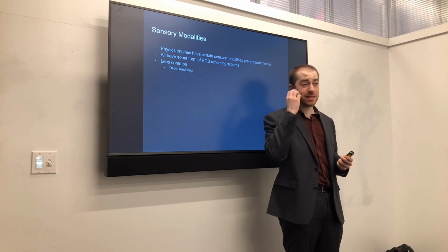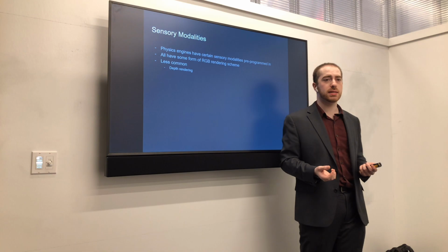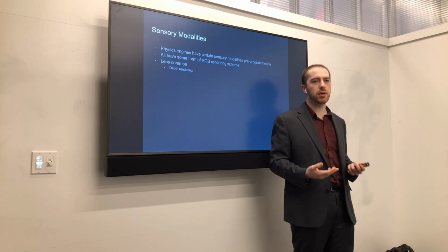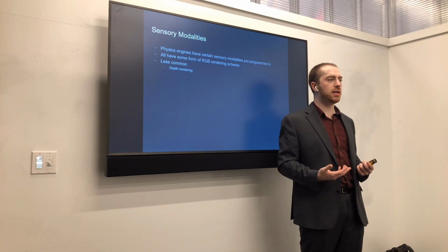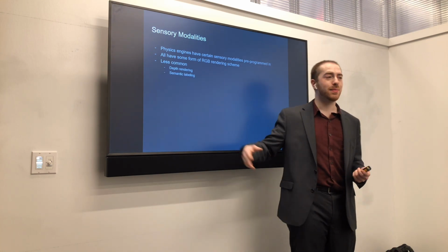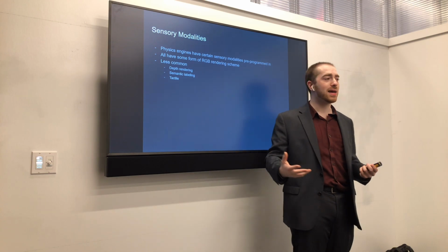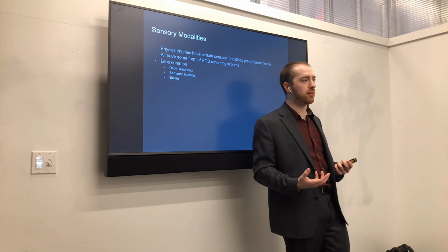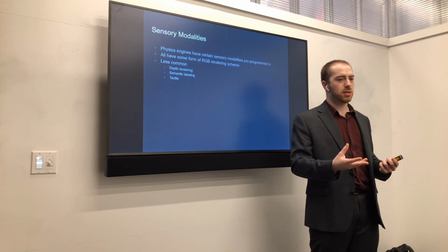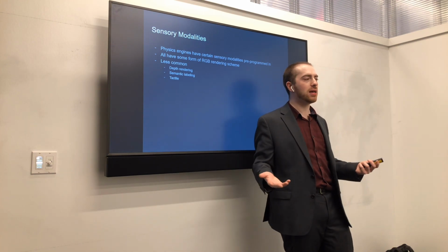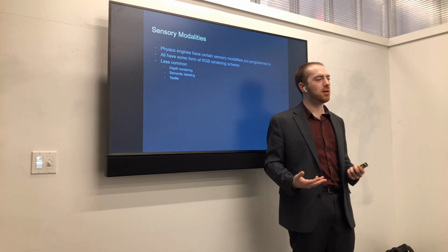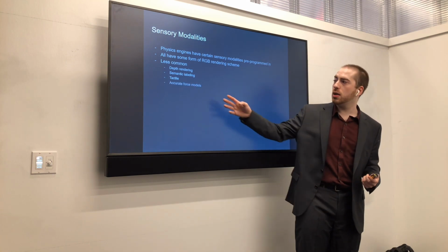Actual structured light sensors aren't usually implemented in these physics simulators. And while OpenGL depth rendering is usually good enough, it's not going to give you the same resolution as in the real world. Semantic labeling comes from manually annotating different images. Tactile is kind of bespoke for the different robotic arm you're using, so they approximate it by just checking if it collides with something, and that's not always going to be the same as the real world.